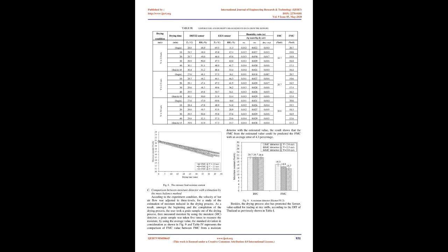The effect was a slightly decreased drying time because the mass was reduced, which made the paddy move through the drying chamber faster. However, at the beginning of the drying process, both sensors sent data values to the MCU, which read and recorded the properties of air as shown in the DHT and EE31 sensor columns in Table 3. B. Estimation of the final moisture content.